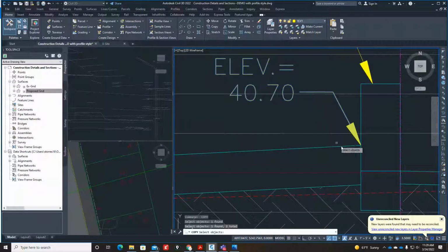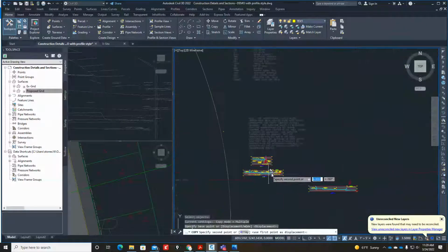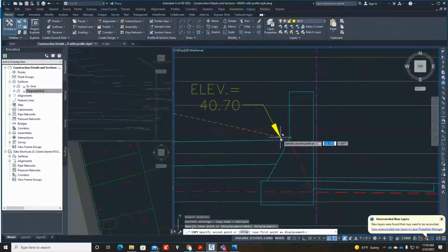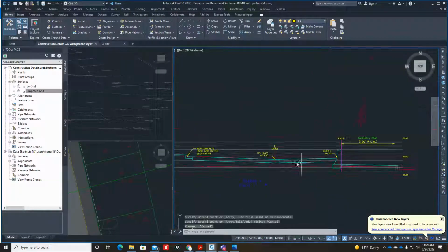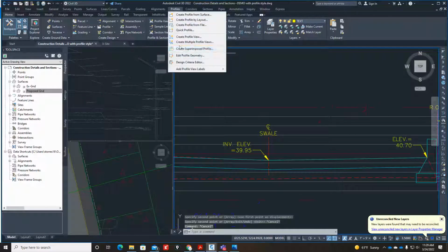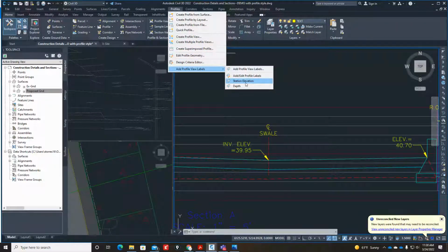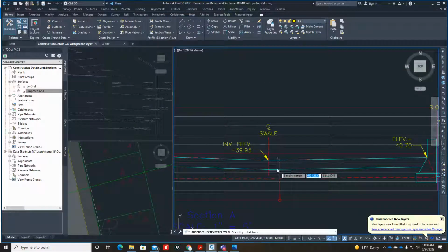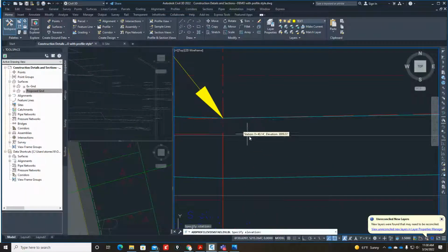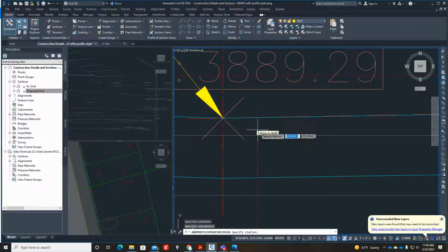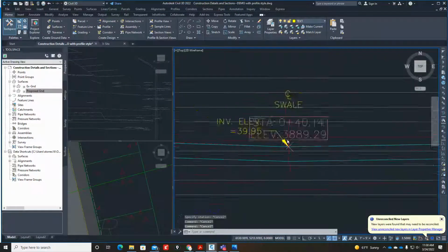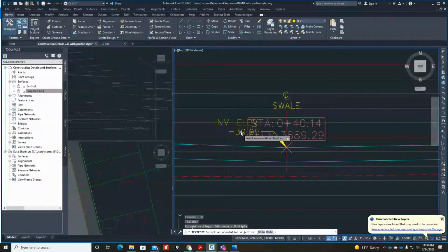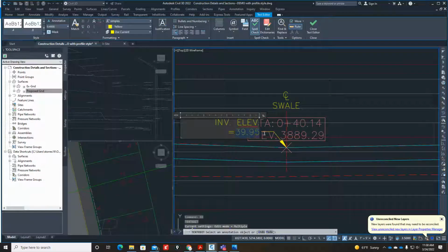Copy these notes right in here from that endpoint over to this endpoint right here. Don't forget to label the elevation on them. Station, elevation, sorry. You pick that point right there. And that elevation happens to be 89.29. So you label the text, or edit the text, sorry. 89.29.